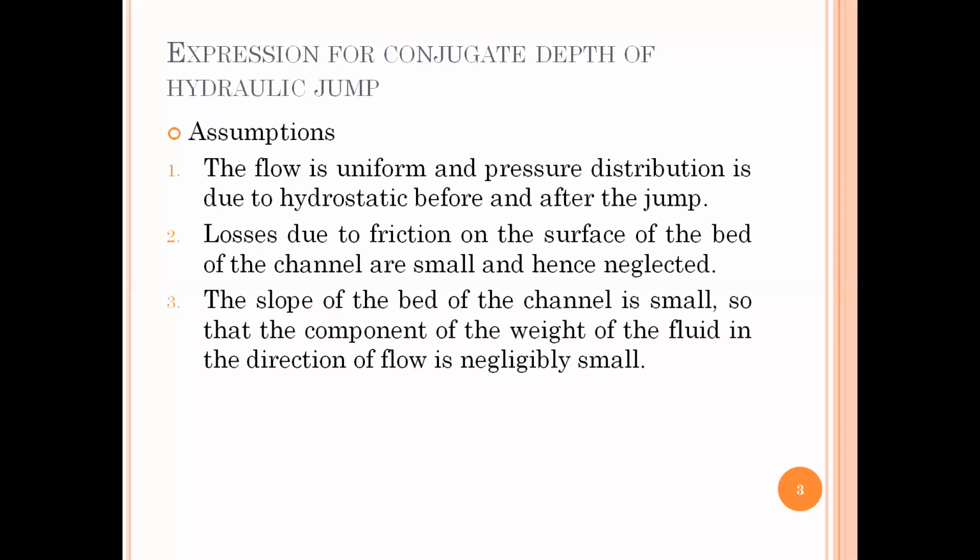Remember that the loss due to friction is between two surfaces. Here it is water and the sides and bed of the channel, which we are neglecting. And the third thing is that the slope of the bed is very small. Remember, we give a very small gradient to any channel. I'm assuming it is small so that there is no component of weight. If I resolve the weight in the x and y direction, there's a small component which causes it to flow. I'm saying that is negligible. These are all assumptions; actually, it has to be counted. For simplifying my equation, I'm assuming everything is negligible.